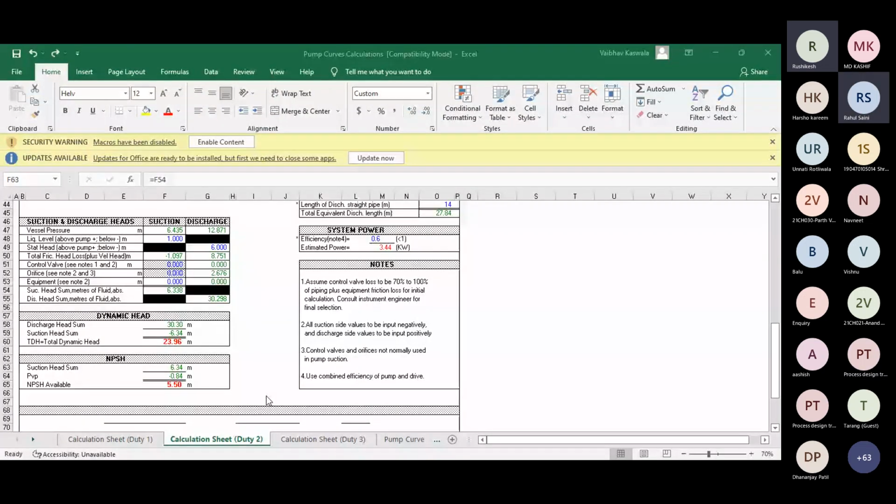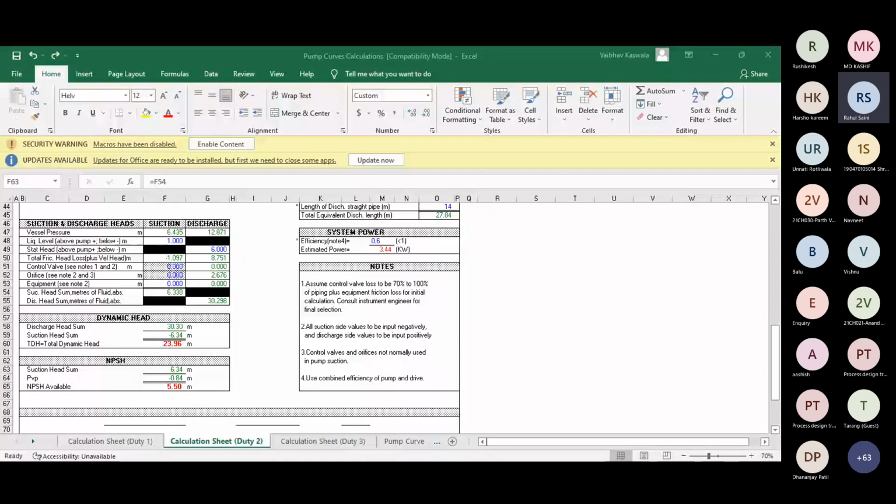And one doubt is that the pump head, you're saying the pump head is not changing, it is the intrinsic quality of the pump design as well. Yes. But while I'm changing the discharge line size, the pump head is changing, no? Am I correct? That is the system curve I'm saying. That is not the pump head. It is a system curve.